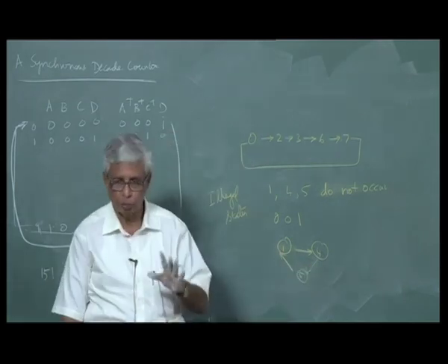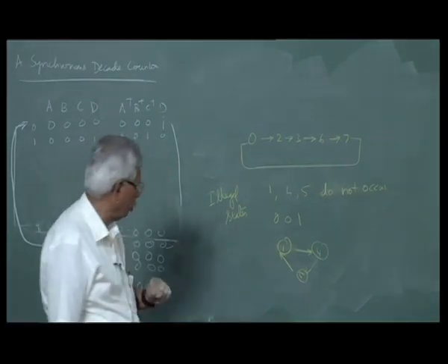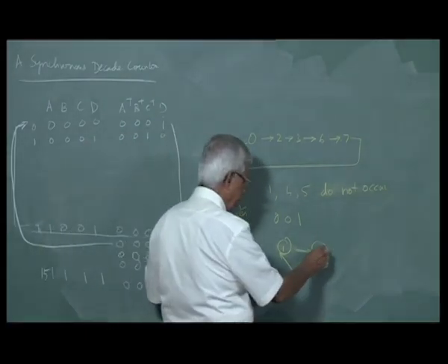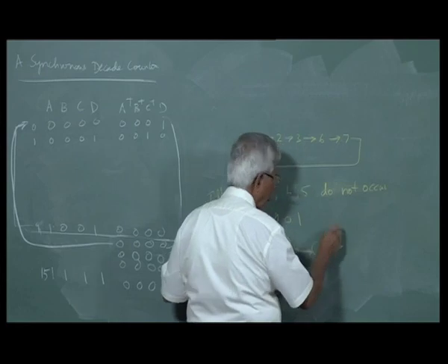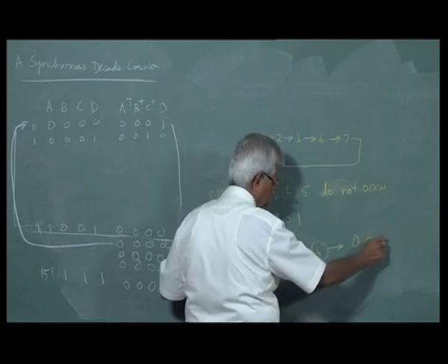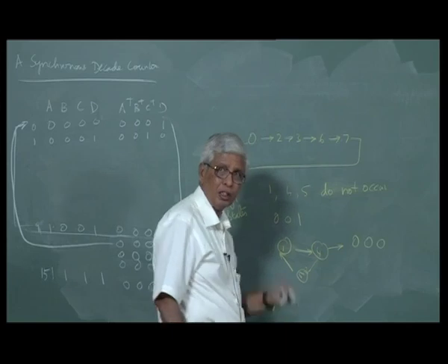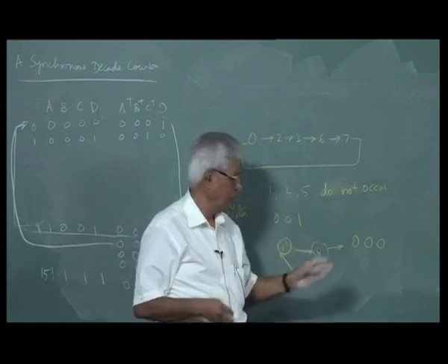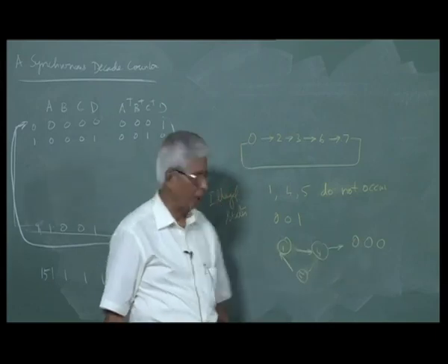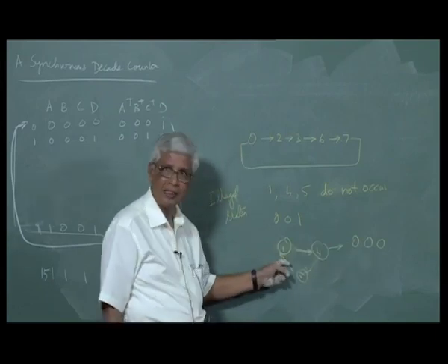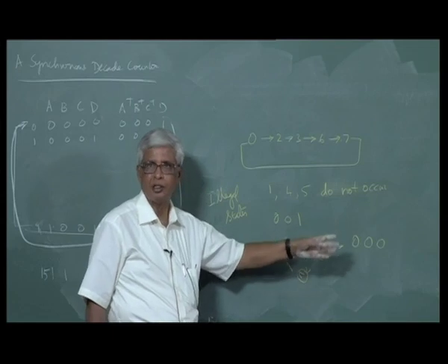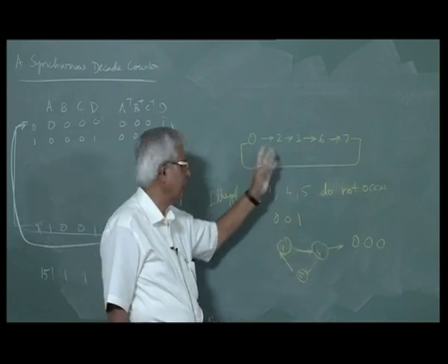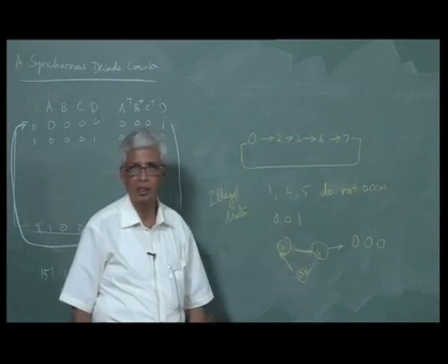It's an illegal loop. For that, I will deliberately put a 4 in the count sequence and put 000 as its next state. Even though it is not required, I will make sure one of these states has next state 0 0 0. If I do that, then it will fall into legal states.